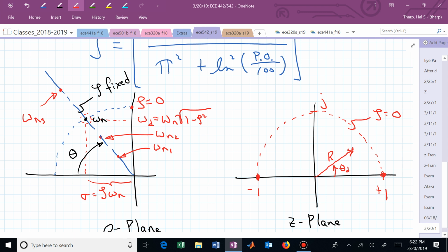Now, suppose that I change that zeta value. What happens when I change the zeta value? When zeta was 0, I was vertical, wasn't I? When zeta is equal to 1, where am I? Then I'm all the way here to like a critically damped position. And now natural frequency is really a real damping amount. The frequency is really sort of the exponential decay speed.